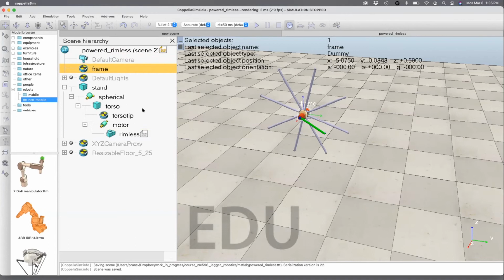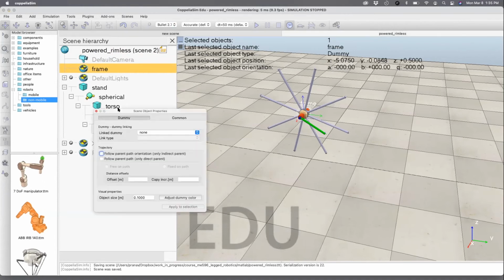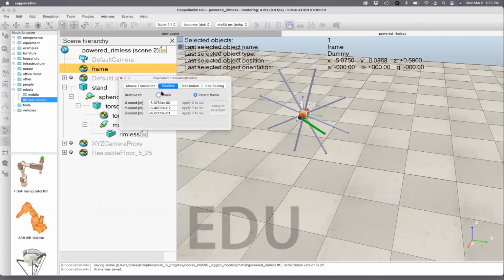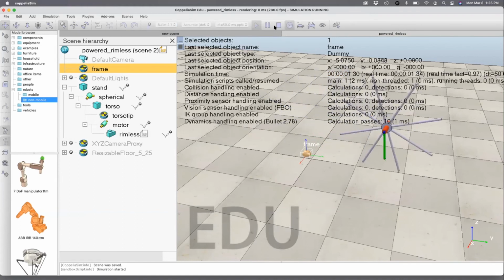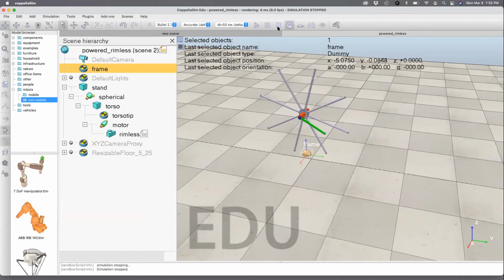child of the motor. Open the frame, go to the translation aspect of the frame, and here instead of 0.5 just say 0. Escape to world frame. It's the world frame, it should be 0. So now it's right below. Okay, so you got it down, and if you let this go, it's going nowhere because it's not associated with anything. But we will basically make it move